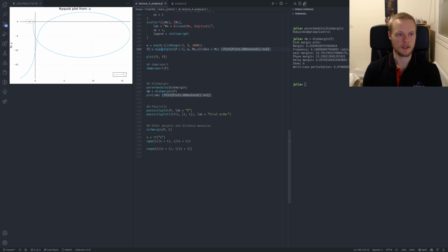That's also partly why we like to draw this circle in the Nyquist plot rather than just looking at gain and phase margins. We really want to stay outside of this circle, because we can come up with systems that more or less fool the classical gain and phase margins too. So we can have a system that has a very high gain and phase margin, but it's still very close to unstable.